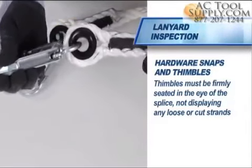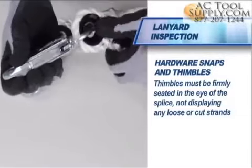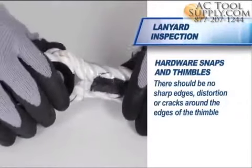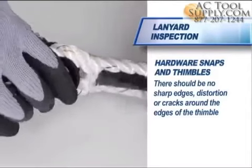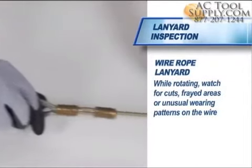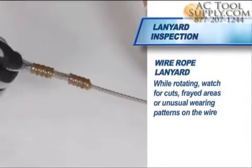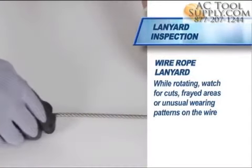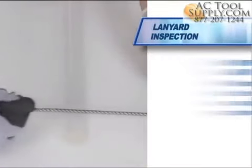Thimbles must be firmly seated in the eye of the splice, not displaying any loose or cut strands. There should be no sharp edges, distortion, or cracks around the edges of the thimble. Always wear gloves when inspecting a wire rope lanyard. While rotating, watch for cuts, frayed areas, or unusual wearing patterns on the wire.